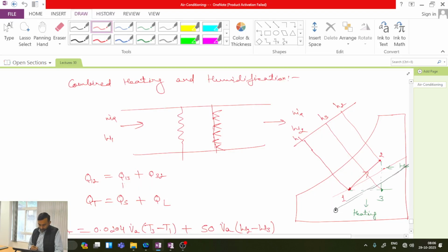Okay, good morning. So in the previous lecture, we have been discussing different psychrometric processes, some of which were pure heating. Then we also attempted humidification. And while we were doing humidification, we found that achieving pure humidification is a challenging process because we have to maintain the enthalpy of the water vapor which we are seeding into the moist air equal to that of the moist air. Only then will we be able to achieve pure humidification.